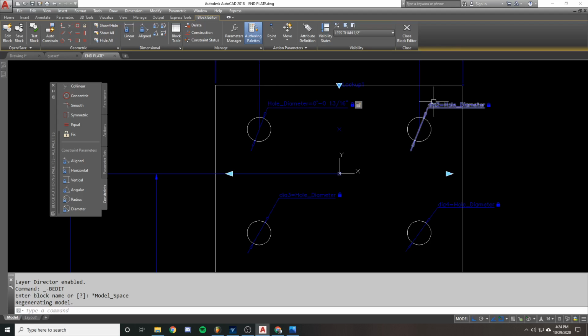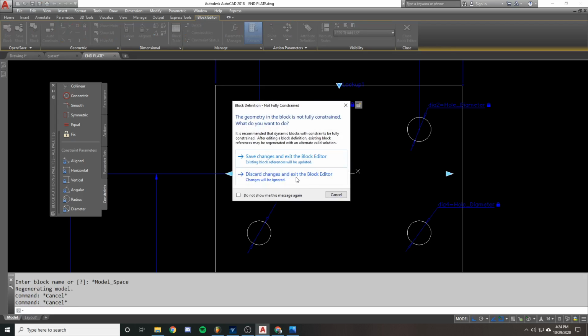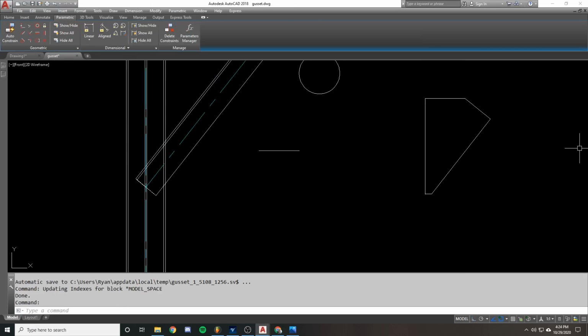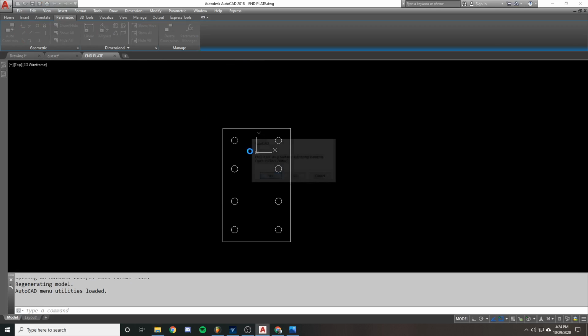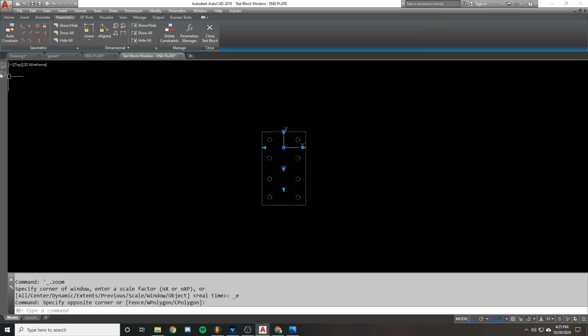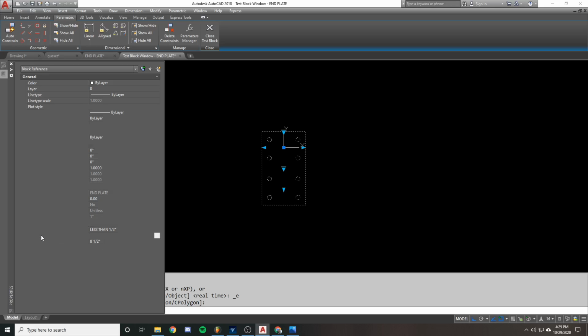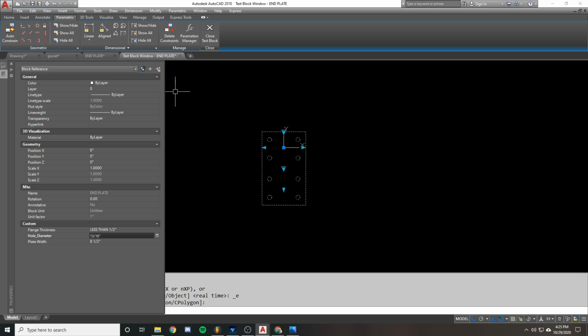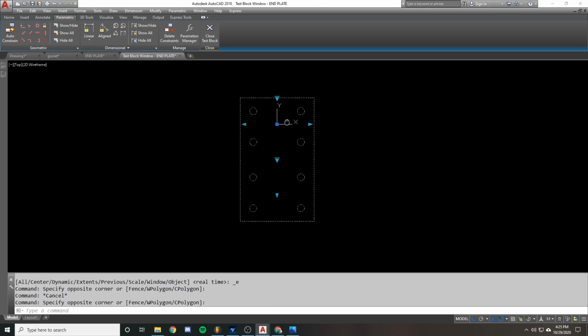And the reason these just say dia1, dia2 is because they're just generic names, right? And this one, actually, I gave it a name, hole diameter. And the reason it's like that is because when you select this block, did I close the whole thing out? I did. Actually, I just want to test it. Because when I go look at this block and I look at my parameters here, you can see hole diameter is a named parameter. You wouldn't want just D1. It's always a good practice to name anything that's going to show up in the properties menu. Give it a proper name rather than just length 1 and diameter 1 and whatnot, because you'll know what it means at that point.